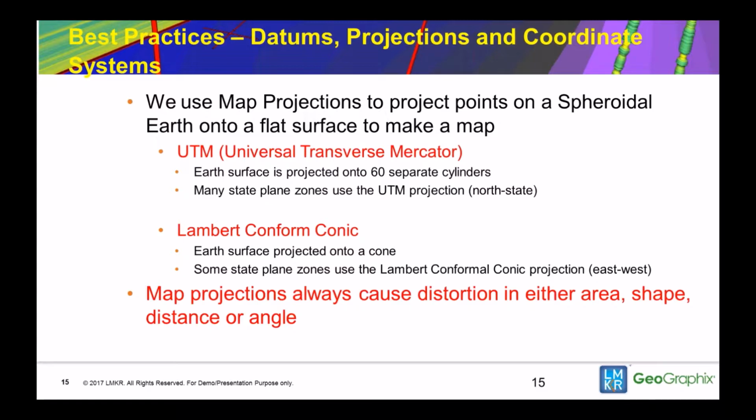So let's say you had a globe that was a perfect representation of the surface of the Earth, and you were spinning it around, when you looked at two locations on the surface of the globe, there is no distortion. But whenever you project onto a flat surface, there's always going to be distortion. And it's sort of a pick your poison thing. So if you were in polar areas, you wouldn't want areal distortion. So in a lot of cases in polar areas, planar projections are used.